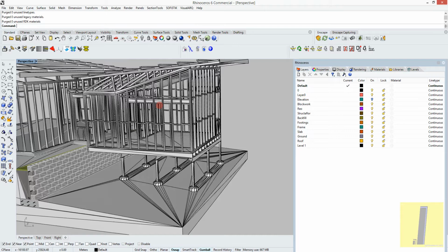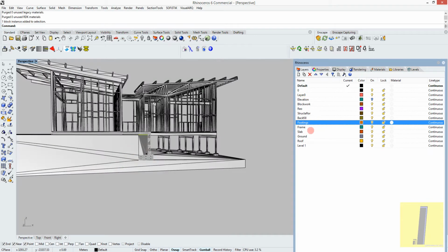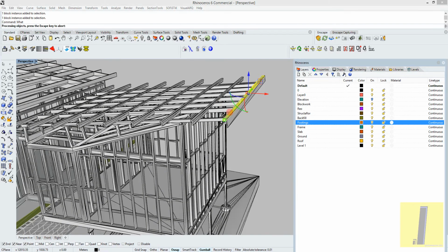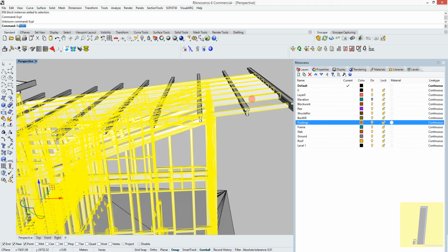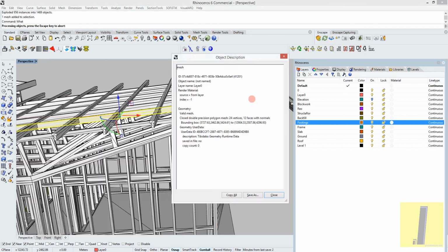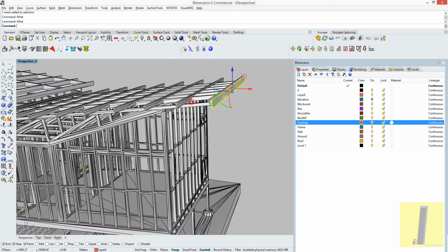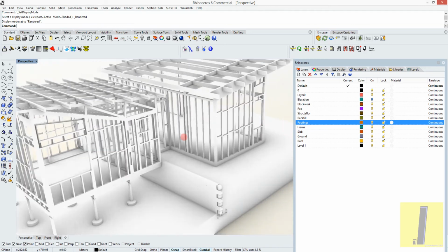Yeah, so the layers, I assume they came correctly from the original SketchUp layer system. And the geometry came as a block instance, but if I explore them, because the original SketchUp model must be mesh geometry, it came as mesh geometry in Rhino. So the interoperation between Aecosim and DWG also works quite well.